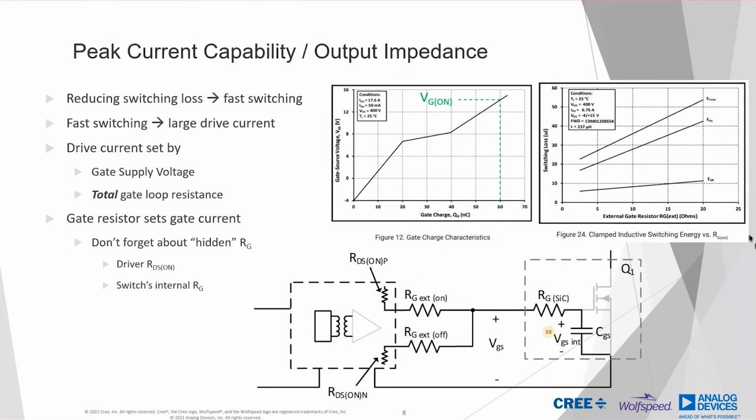One thing I want to mention when you're looking at different gate driver data sheets is that there are different test conditions in how manufacturers report their gate driver output currents. Some specify currents that are achieved during a very short circuit pulse where you short the output, while others use currents that are measured when you have some realistic gate resistance present. So you do need to be careful when comparing specs from different devices.